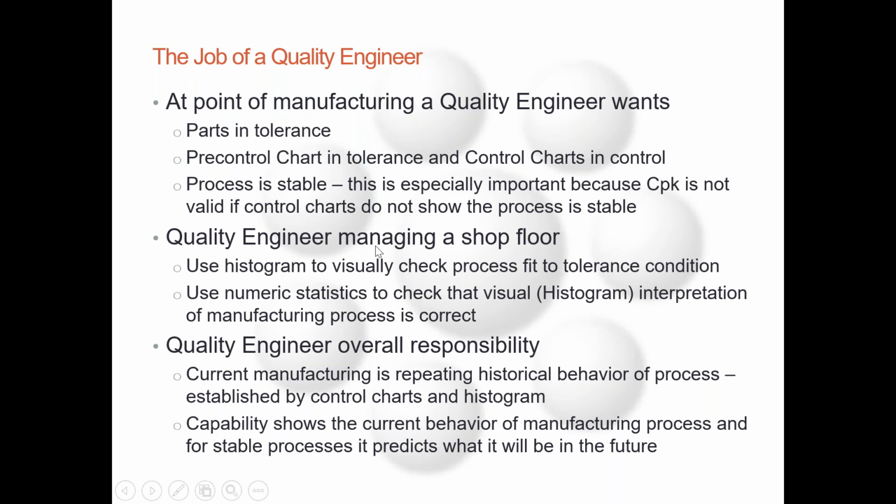So the manager of the shop floor is going to move on to the histogram. Remember how that's even taking a further step back than what was happening at the detail level with the control charts. The histogram is now a generalized look at how the data over that week or month is spread out and how it fits the tolerances. And they're, again, trying to make sure that they've got the manufacturing process running at its optimum performance.